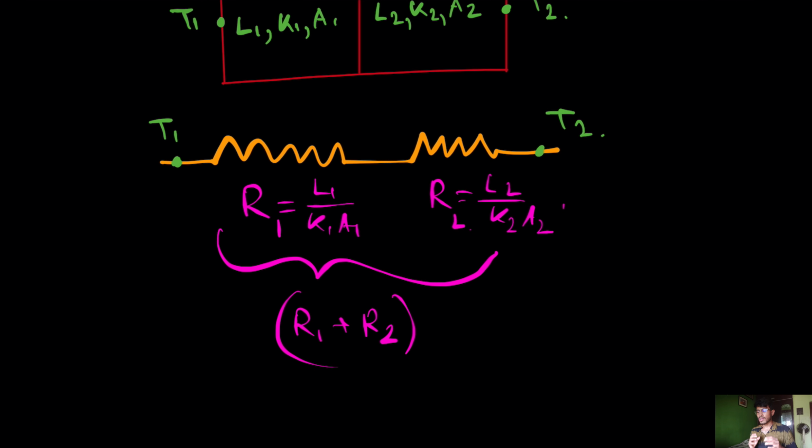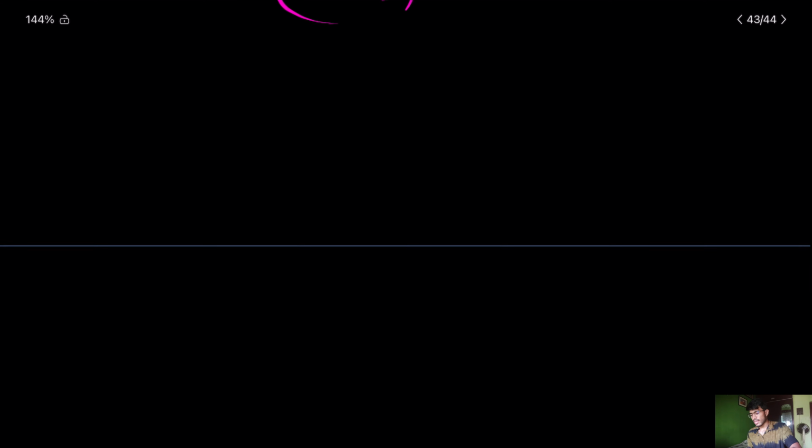So the main crux of the matter is that the thermal network is equivalent to the electrical network. So you can do all the analysis with the thermal resistance that you have already done with your electrical resistances. That is, if two blocks are in parallel in case of a thermal network, then you can convert that into a single block just by modifying the thermal resistances.